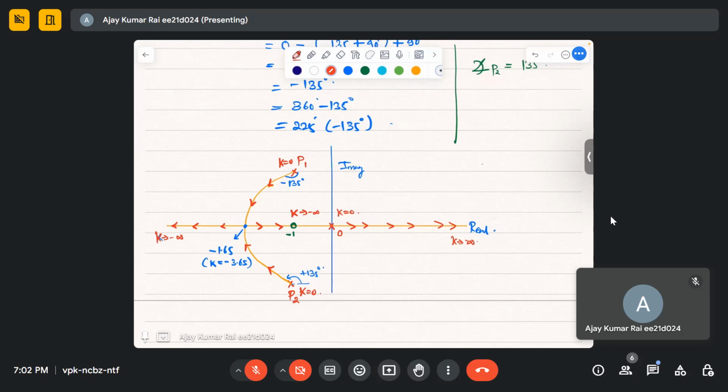And also we know k is less than 0. That's why this is plotted for k less than 0 for negative feedback. So you can put any value of k. What is happening? You just focus on this part. For any value of k you take, we are having closed loop poles on the right half plane.